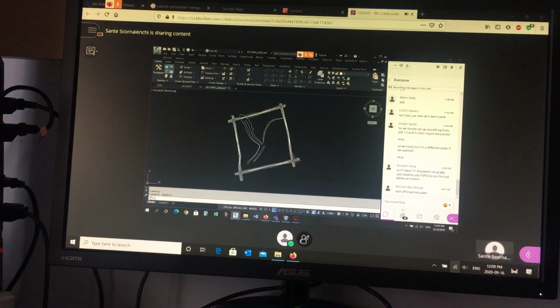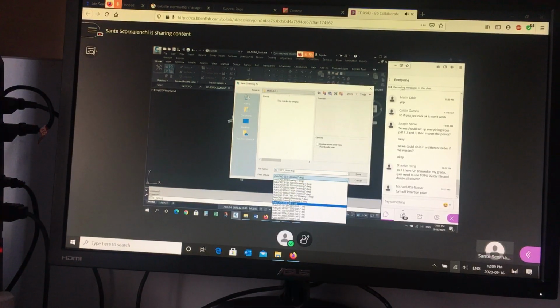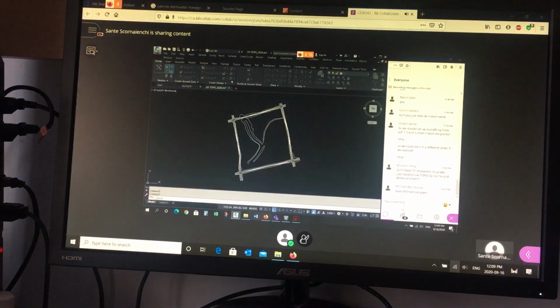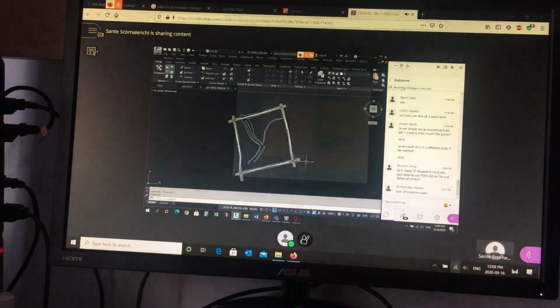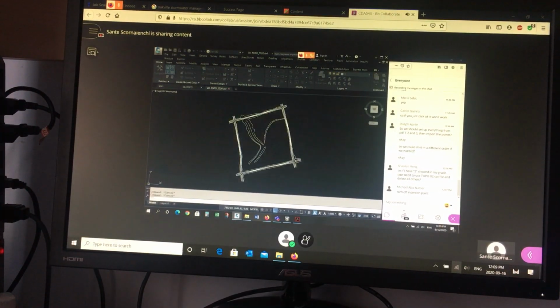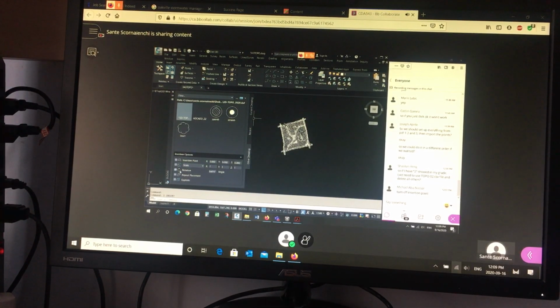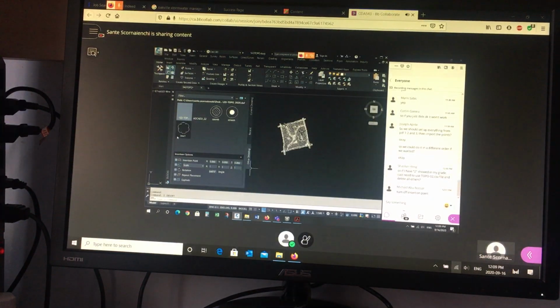Save that. And you can save it as a DXF again. Just overwrite the file. So overwrite that file as a DXF. Save it. Say yes. Close it. You save it once, and then we can go back to here and insert it. It should work. So let's try to insert. Everything's good. Pick the file. You should be able to insert it. It might ask me to overwrite it because it's already there.